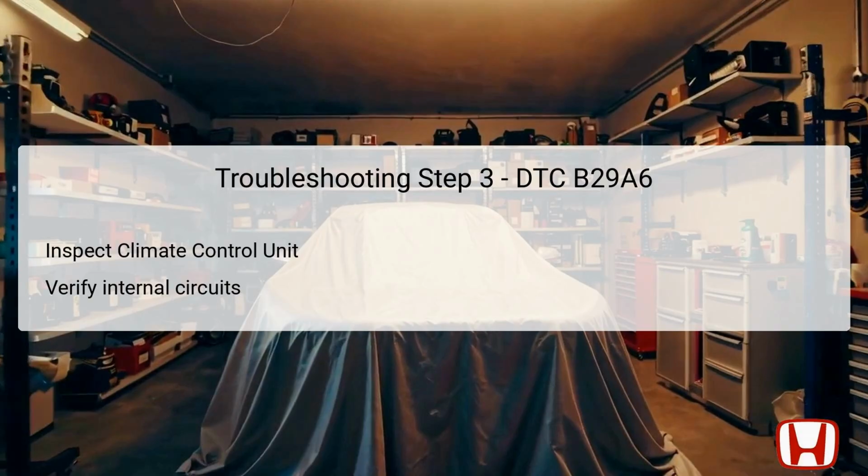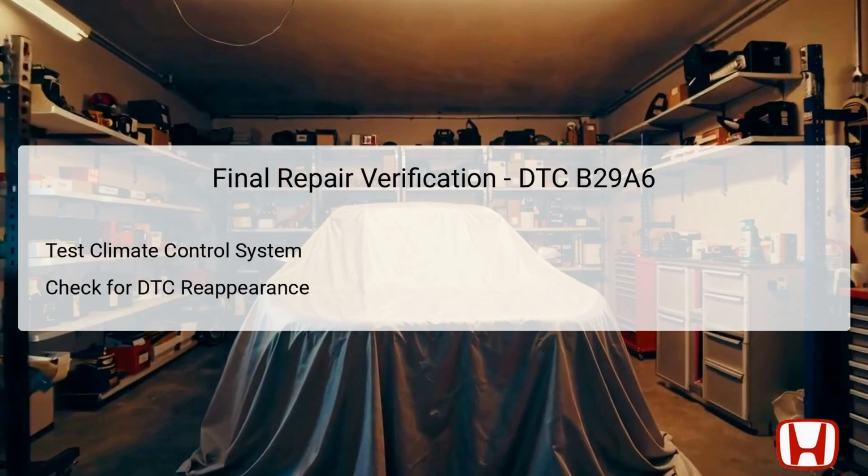If the climate control unit fails to deliver this voltage or exhibits other abnormalities, it suggests a malfunction within the control unit itself. Resolving this issue may necessitate repairs or replacement of the unit to restore full functionality to the vehicle's climate control system. Once the troubleshooting and repair process is complete, it becomes imperative to conduct final verification tests to ensure that the climate control system is functioning correctly.